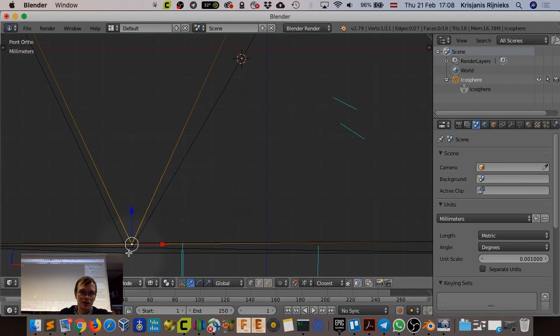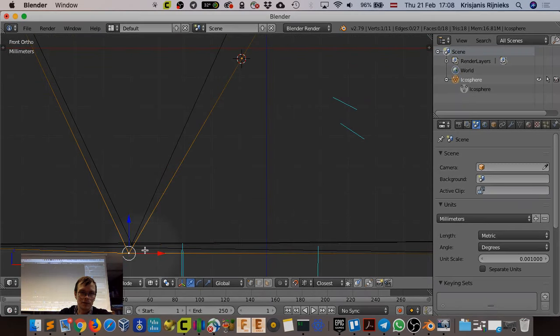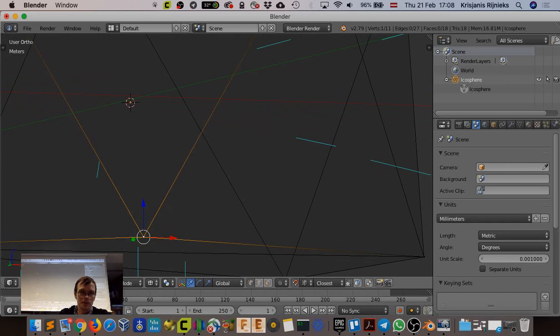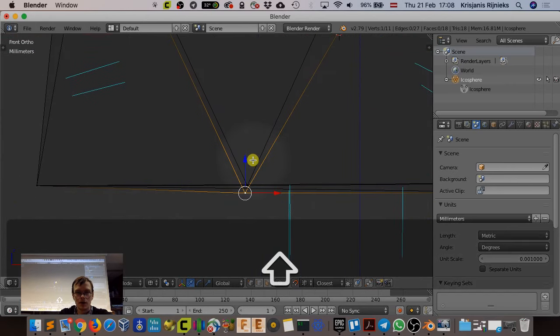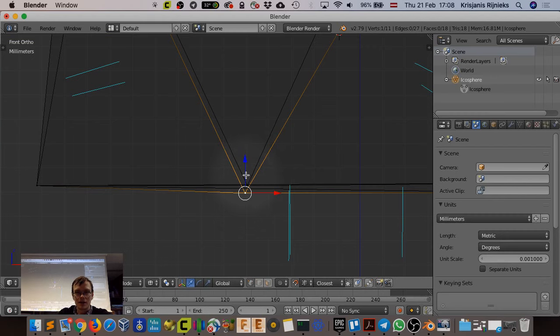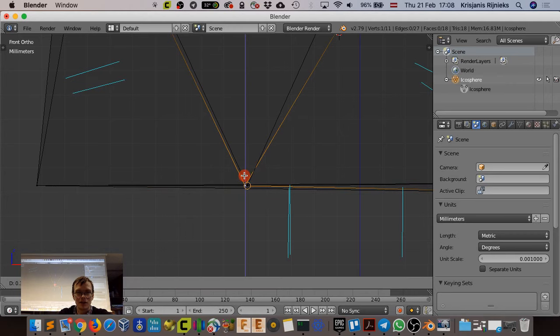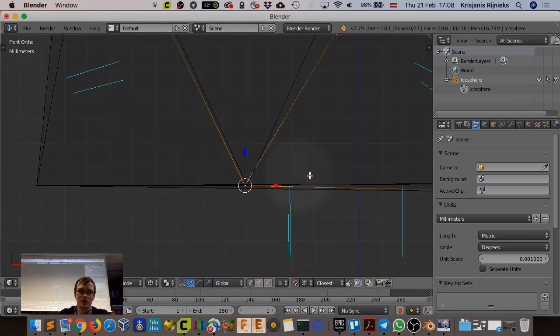So first what I did, I selected the vertex. I'll reset it to front. So with the right click, then with the left click, I click and drag the Z-axis, and I move the mouse cursor, I hover the mouse cursor above one of the vertices, about the vertex that I wanted to snap to on the Z-axis, and then I release.